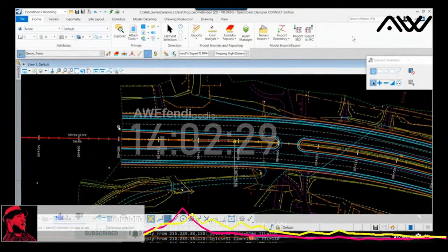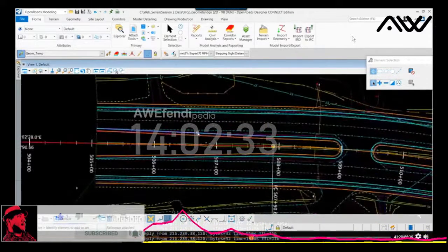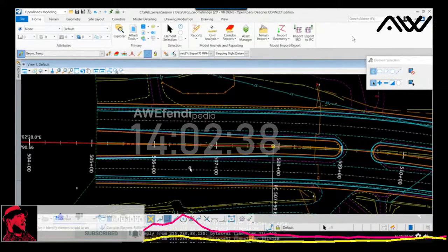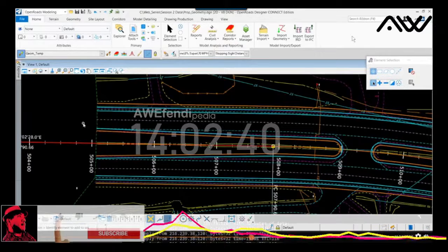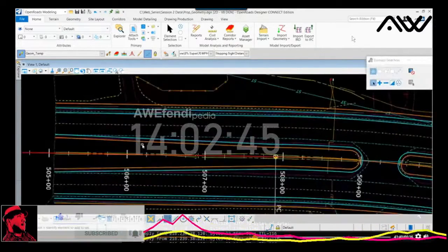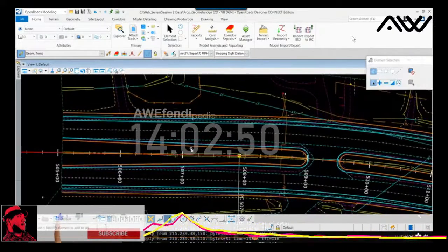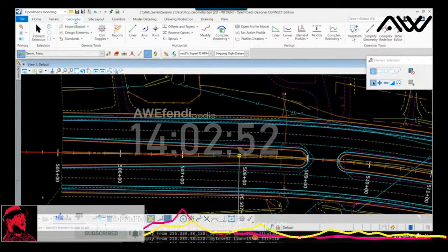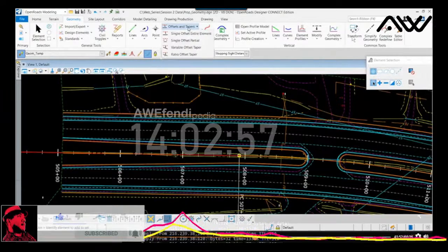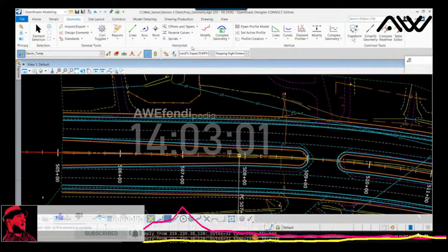Okay, so I'm going to create these taper elements using civil or OpenRoads geometry. Currently, these are just MicroStation lines. This is just a graphics file of the proposed layout. And I'm going to create these so that Scott can use them next week as control lines to control his width of pavement. All right, so to do that, I'm back under the geometry tools. I'll go under the horizontal menu, go to offsets and tapers. I'm going to use this command called variable offset taper. And again, I'm going to follow the prompts.